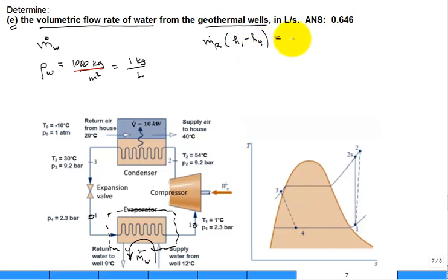And so it's the mass flow rate of the well water times, and now if you knew the change in enthalpy, but we're not just going to do a change in enthalpy, we'll use the specific heat of the water. And because it's water, you don't need to put C sub P, you can just use C for the water. It's like C sub P is equal to C sub V. It's just one specific heat. Drop the subscript for an incompressible substance like water. And then we multiply by the high temperature coming in minus the low temperature exiting for the well water.